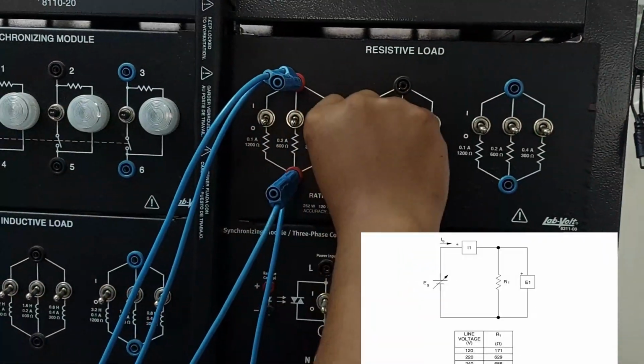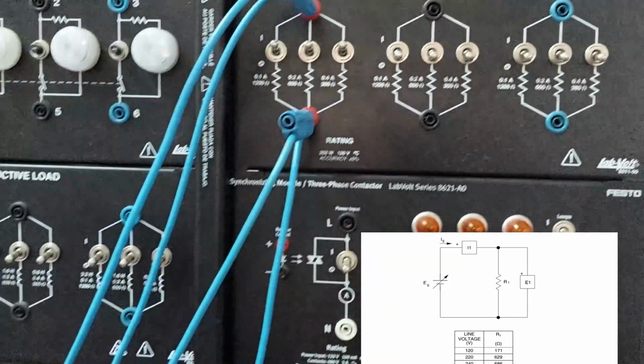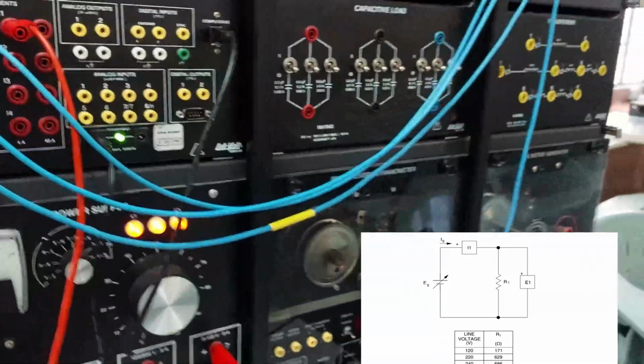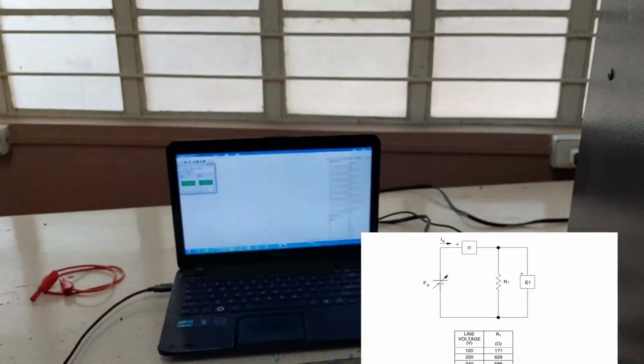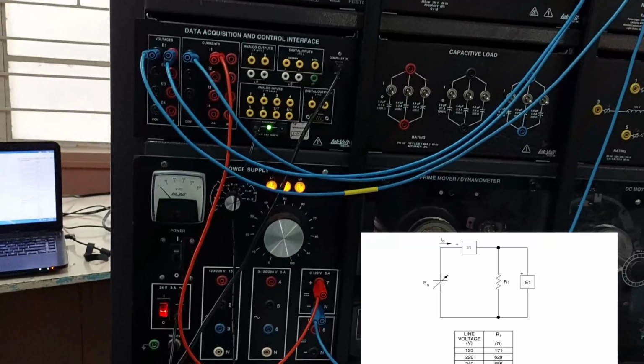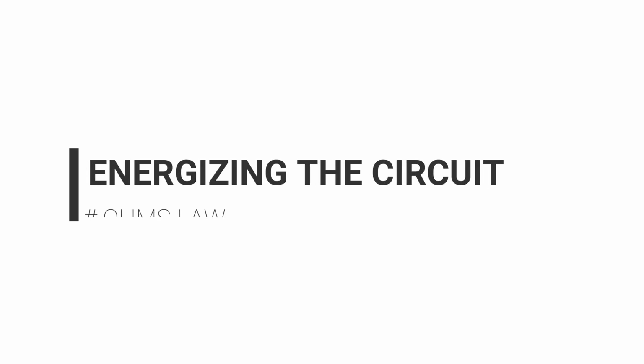And then, based on our circuit diagram or in our experiment, the amount of resistance that is needed is equal to 171 ohms, which is the parallel combination of your 600 ohms, 300 ohms, and 1200 ohms. After setting up the circuit, let us display the metering application and select Setup Configuration File ES11-1 DAI.